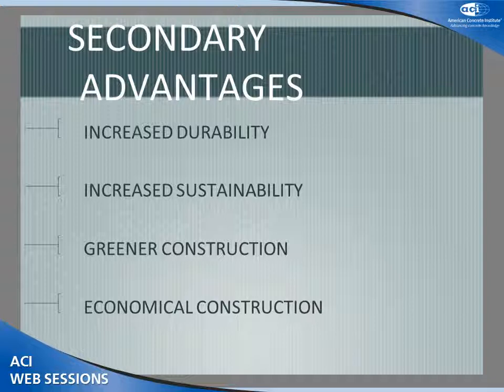The answer is that Type K is chemically reactive, and normal variations in the raw materials cause changes in the expansion characteristics of Type K as manufactured. Similarly, any changes in the concrete mix at the concrete supplier or on the job site can change the expansion rate and the component dosage amount required in the final product. The concrete is placed at the project site.